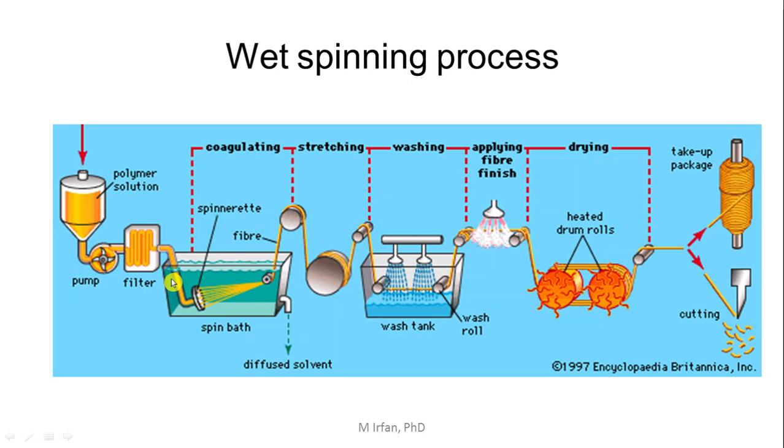And since this is a wet spinning process, we can see that the spinneret is placed in an aqueous solution bath, where the formed fibers are then exposed to a wet aqueous solution, due to which this technique is known as the wet spinning technique.